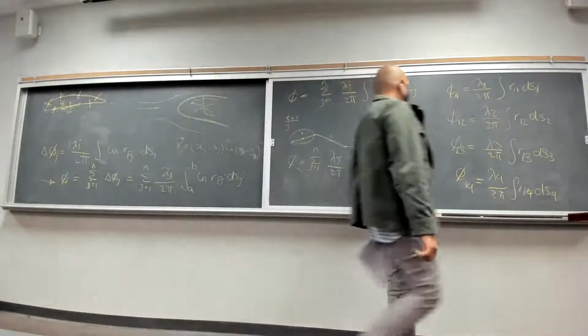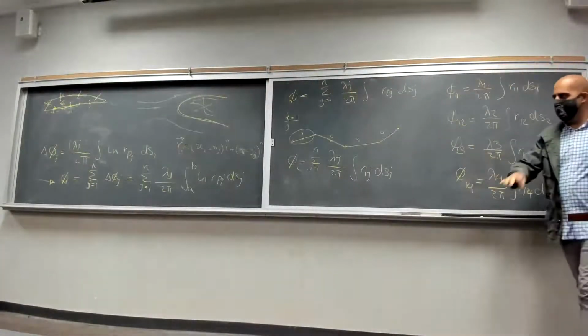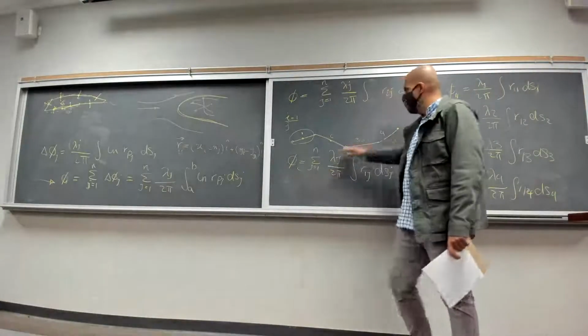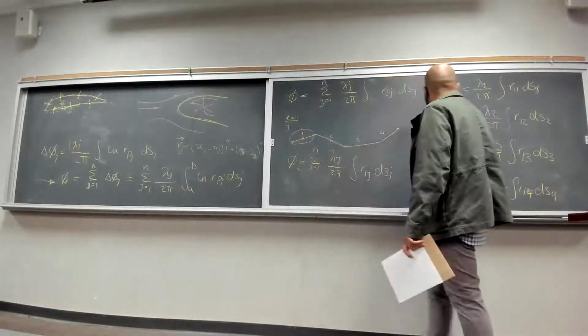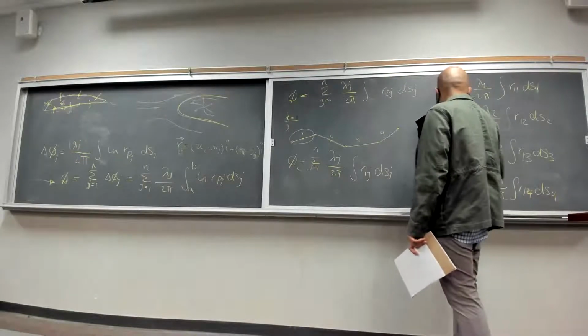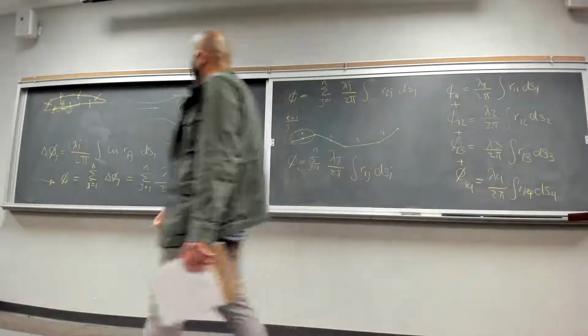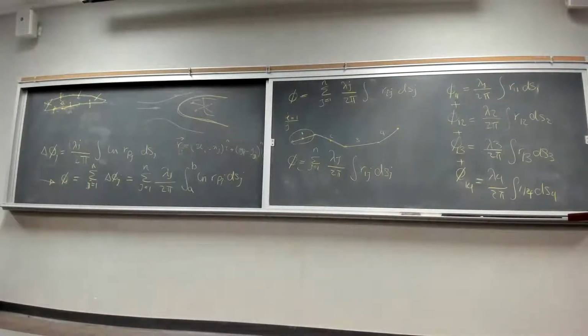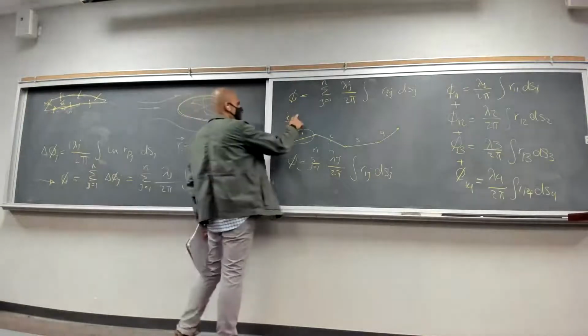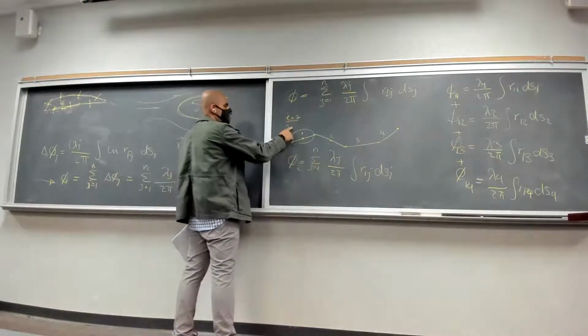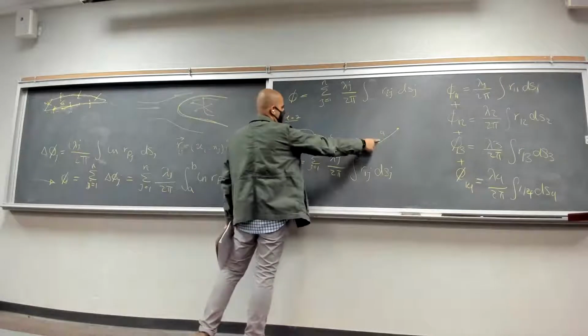Okay. So are we clear here? And then this phi, the velocity potential induced by all of these panels on this one, is going to be just the addition of all these four. Is this clear? Then you can do the same thing. You can set I to 2 and then move J from 1, then 2, 3, 4.